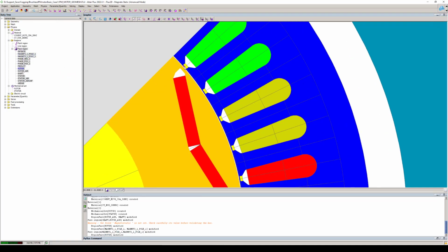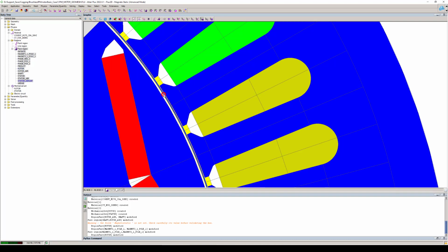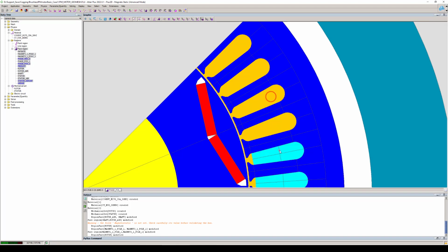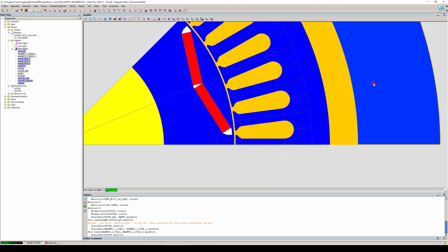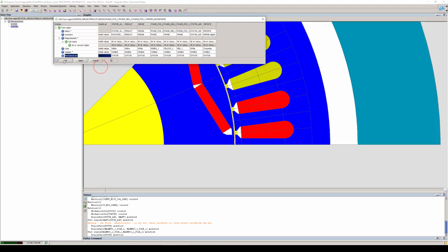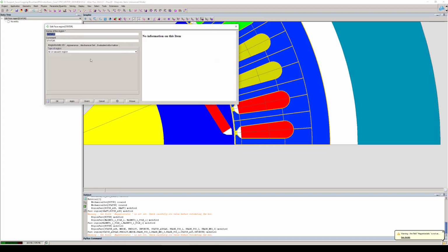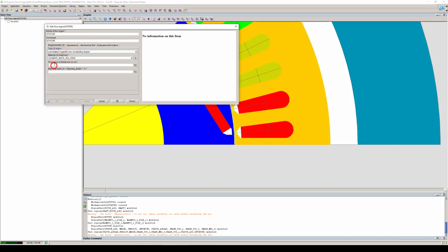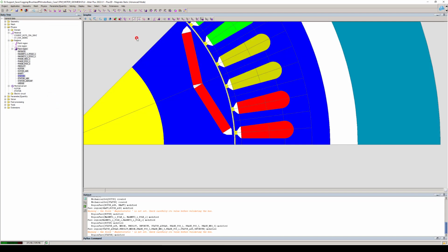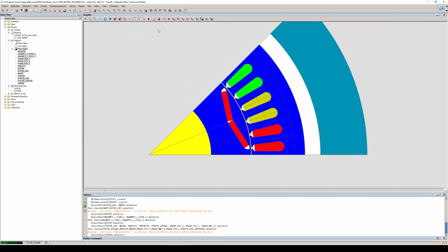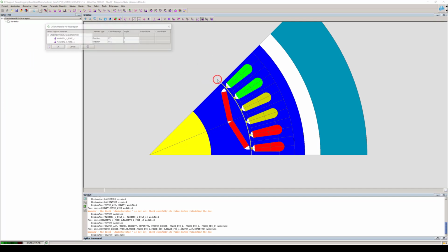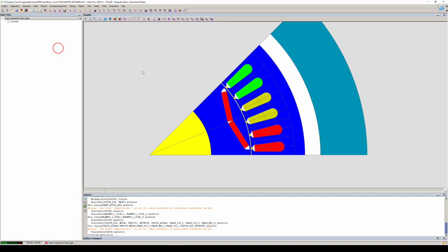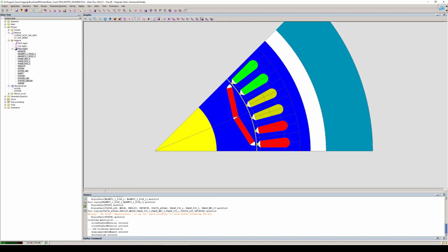Okay, then we have all the stator materials. So this one, this one, this one will all be air region, air, and then stator. And just the lamination will be the only different region we have on the stator side. And here we go. So we assigned the regions. Now we can just orient the magnet. So here we have directly a coordinate system for the magnets in the middle, so I can just orient them very quickly. And now I can prepare my scenario to solve.